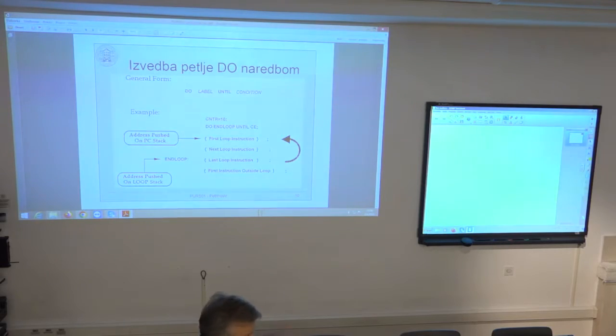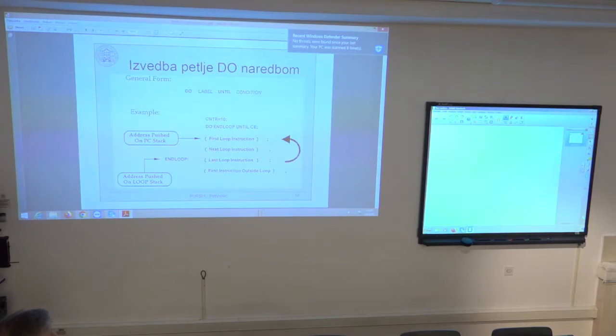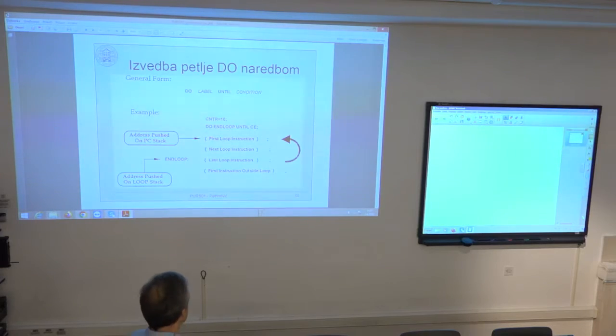You would have to automatically insert wait states until the proper address is finally fetched to have the pipeline full again. But since this is implemented in hardware, it will automatically know whether it has to go up or whether it continues if it was the last instruction in the loop. So you don't have any additional no operations or waits to handle this conditional branching. So it is done without any loss in the pipeline cycles.